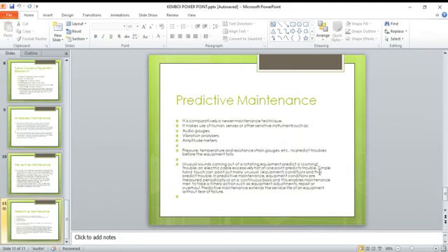So let's now see predictive maintenance. This is whereby you predict that there is maybe a change in vibration or a change in movement of belts, you will see changes in maybe the machine producing an abnormal sound. That is now you predict there might be a problem. Then you will do maintenance.